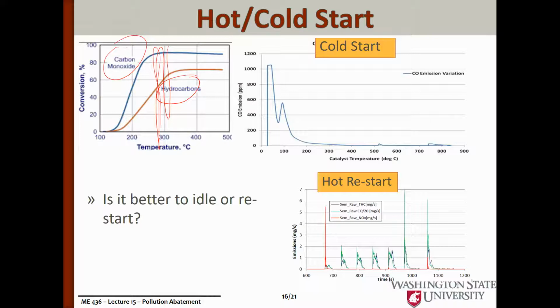And the reason for that is it wants to heat up the catalytic converter first, and then it'll keep it warm just by using the engine intermittently. So a question that comes up fairly often is, since the majority of our emissions on a typical 20-minute drive to work are occurring in the first 2 or 3 minutes of that drive when the engine's cold, when you come to a stop sign, is it better for the engine to idle or restart?